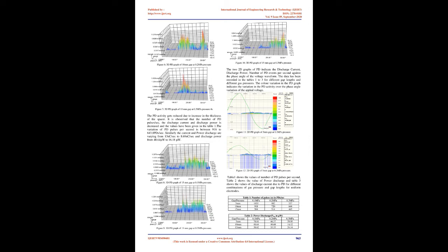Before starting the experimentation, the MPD600 measuring system is first calibrated by connecting a PD calibrator across the test object. The PD measuring system is calibrated for voltage measurement as well as capacitance calibration by applying a certain known voltage much below the inception voltage across the test object. The calibrator is disconnected and the sample is connected to a PD-free HVAC source through a